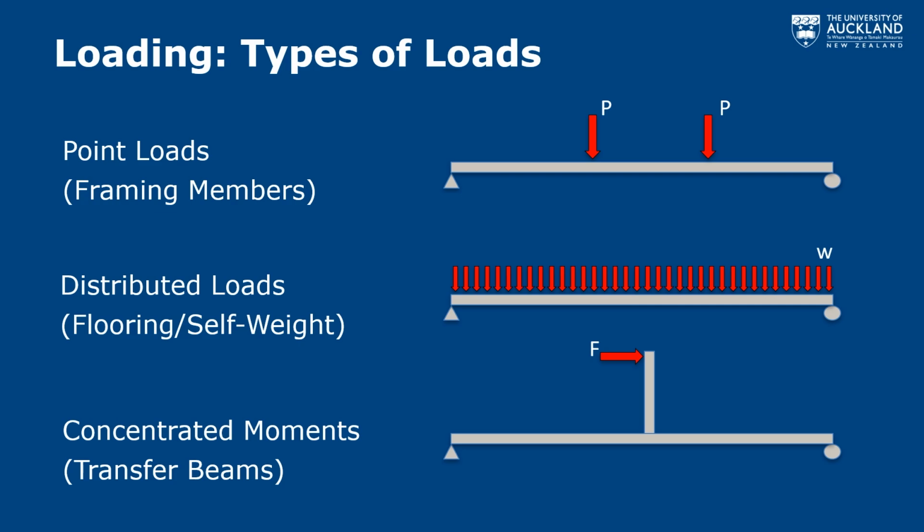If that column has a horizontal force, that force is going to create a moment, a concentrated moment at that point. So those are the general ways in which we go from real life loads into these free body diagram simplifications of these loads, so that we have something that we can analyze for design. And I think that's an important point to concentrate on: these are all simplifications.